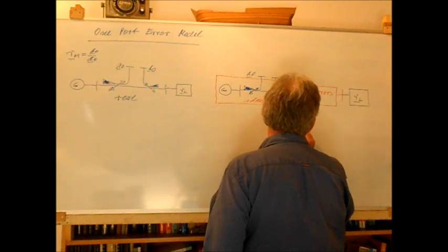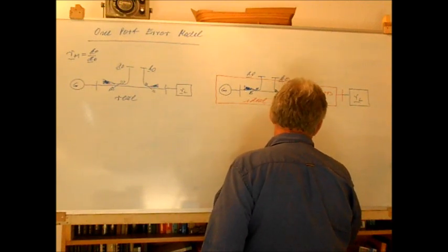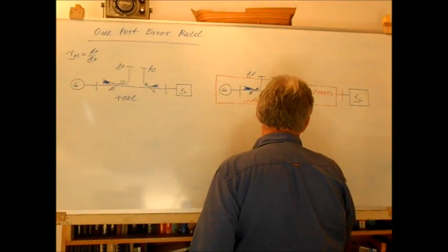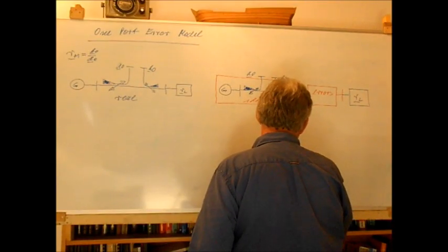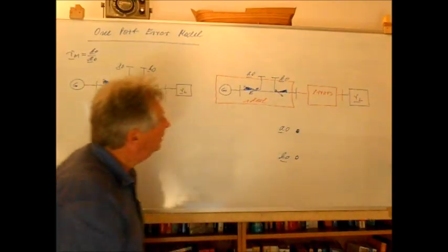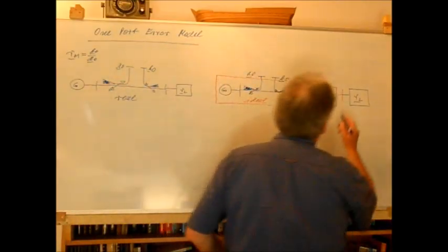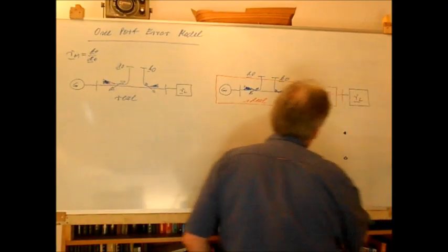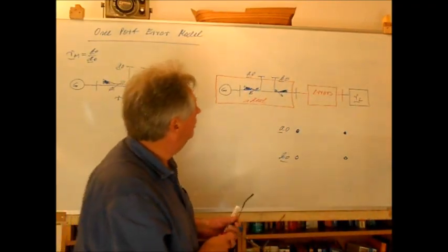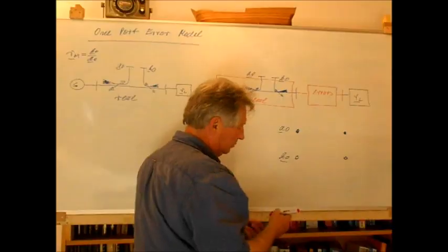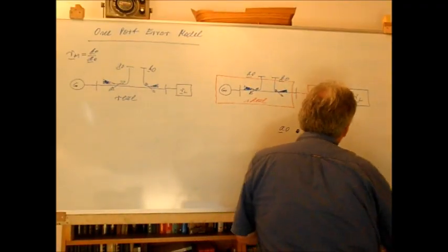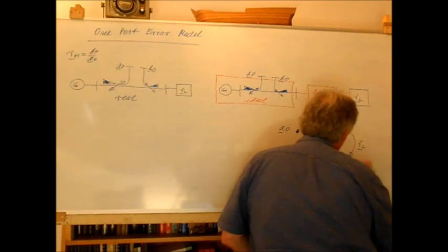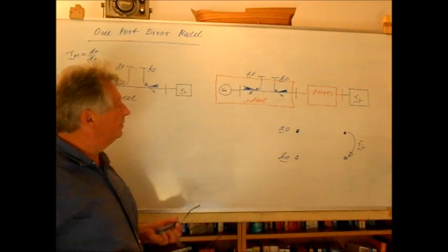So we will have here the measured wave amplitudes, or realized wave amplitudes, B naught and A naught. But here we assume that between the measured reflection coefficient and the reflection coefficient of our load, RL, so-called error parameters are introduced.